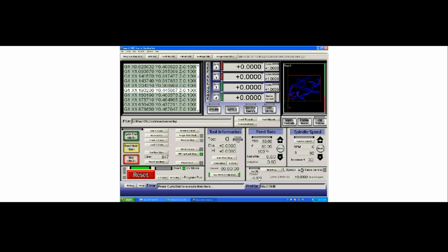This section of the screen here is used for multipass. Again, you don't need to worry about it unless you know how to use it. Generally though, if you have a G-code file which is set to a particular depth, say it's set to cut to -10, you could hit multipass and tell that file to cut 5 times, dropping 2 each time until it hits 10. So it is literally a multipass selector, allowing you to cut a file in multiple passes.